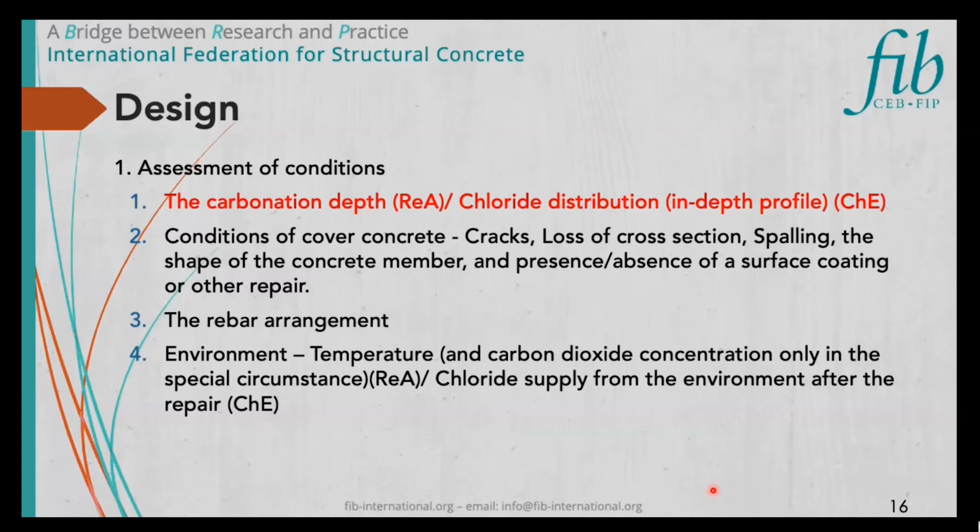Index profile of chloride penetration from the surface to the backside of the rebar is required. Conditions of cover concrete must be checked as it affects the electric current distribution greatly.